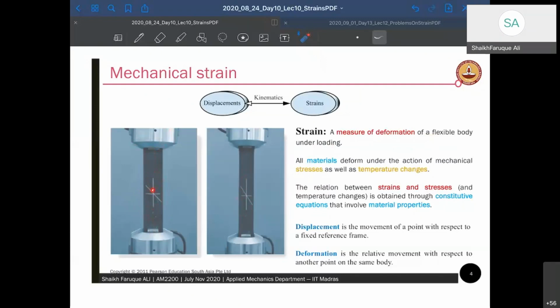If I have the same geometry of a structure, made of the same material, and I just extend the length of this, what will happen? The length will change, right? When you pull it, the longer length will have a longer pull and the shorter length will have a shorter pull, right? So change in deformation is different. But we want to normalize this somewhere. So what we do is we calculate strain. The strains can be because of mechanical stresses or because of thermal changes in the material.